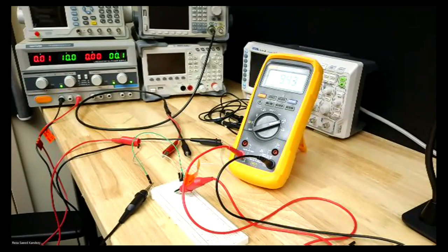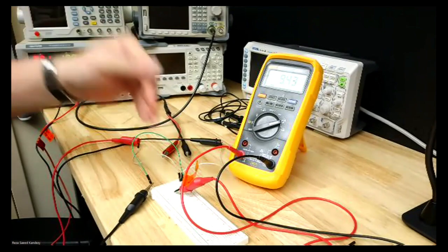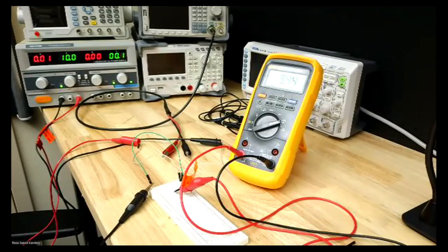Our maximum current was 100 milliamp. We applied a safety factor of 10, which brought us to the 10 milliamp maximum safe current. And choosing this 1K resistance, although it has a tolerance, it has an error in its resistance, and it's actually 983 ohm instead of 1 kilo ohm, we're still under the maximum current that we designed. Okay, so we are good to go on this setting.